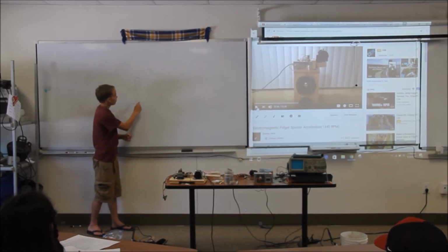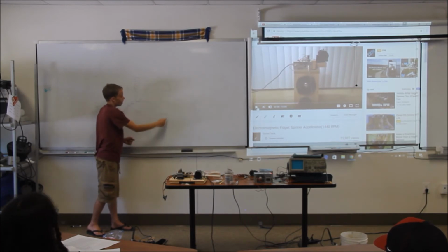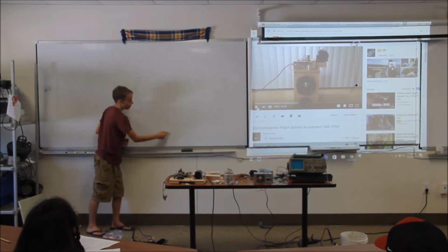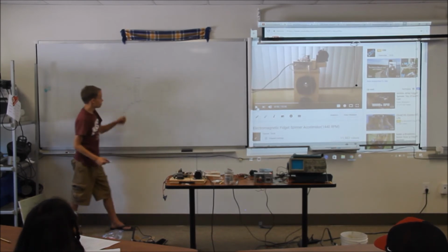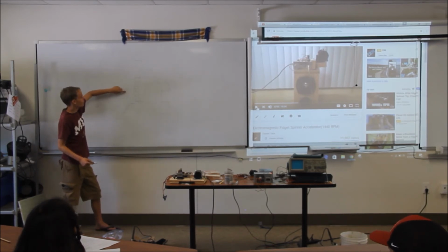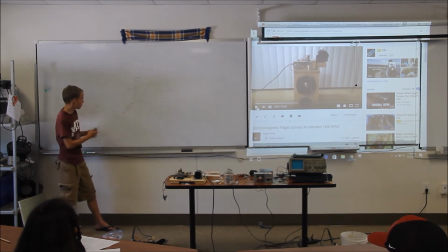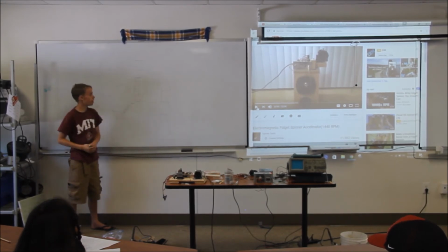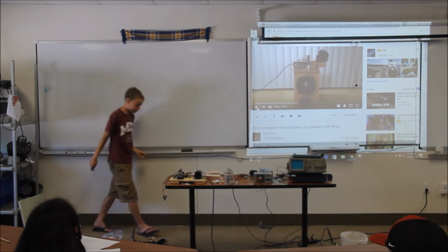Now, when that happens, it'll allow the current to flow through this inductor from positive voltage, through this transistor, and back to ground, which turns this inductor on and causes it to push the magnet of this spinner away. And so every time the spinner spins and the magnet attracts this switch to turn on, it'll cause this thing to push it away, and it'll keep it spinning faster and faster.